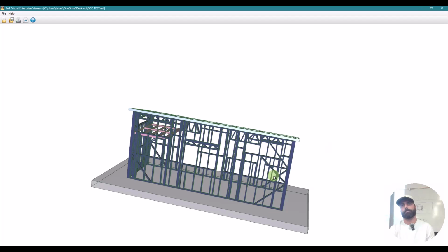We take the Excel spreadsheet, we created our own Excel spreadsheet that takes that, we go into a label maker, and then we put QR codes with the weight and with the panel size and the panel ID. It does a shipping list, so we know where you're at. 100, yeah, exactly. We do an opening list, so the Excel exports all of the openings, and we can do a rough opening checklist, so our clients can sign off on all the rough openings in a single page.